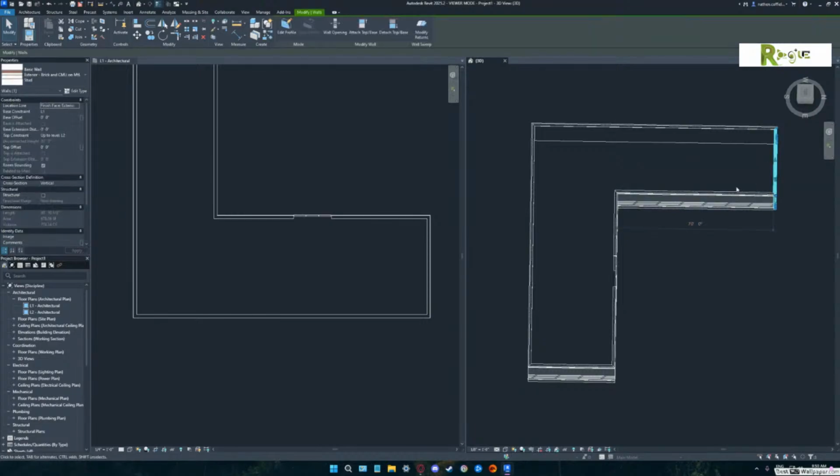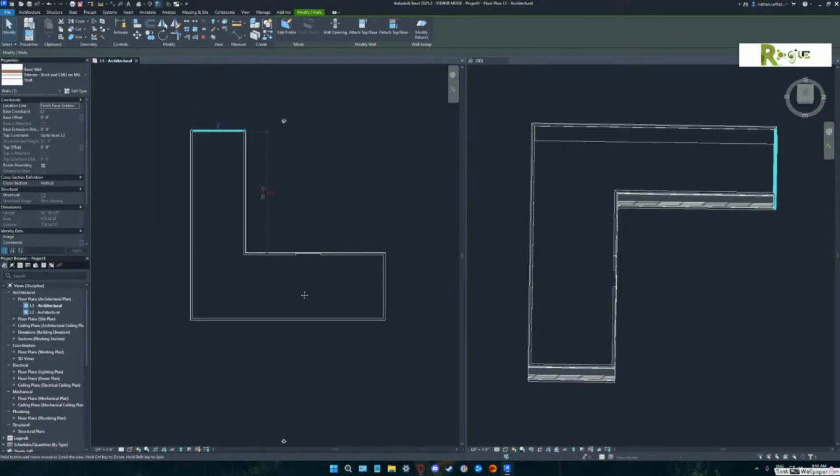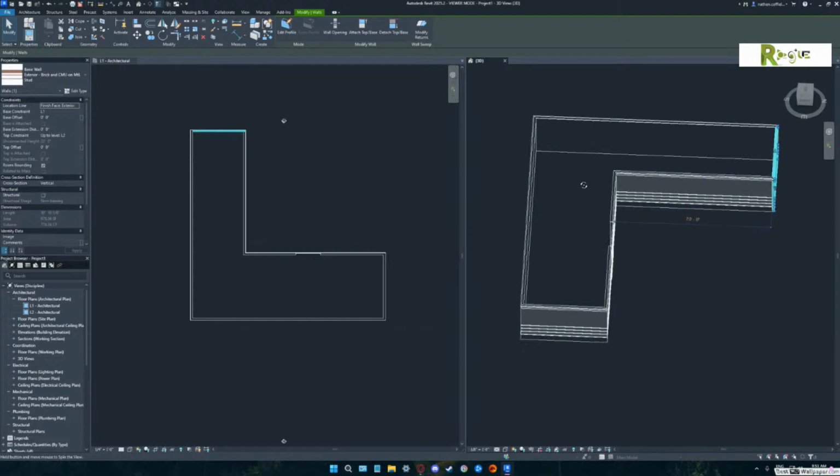That's temporary dimensions. That typically I haven't seen a lot of. So what ends up happening is when I'm teaching CAD people, we typically go back and we throw all those dimensions on and then we make those dimensions good numbers. What I want you to understand is I really started being able to do things fast when I was able to utilize and understand how those temporary dimensions worked. Make sense? So let's hit escape 2 times.